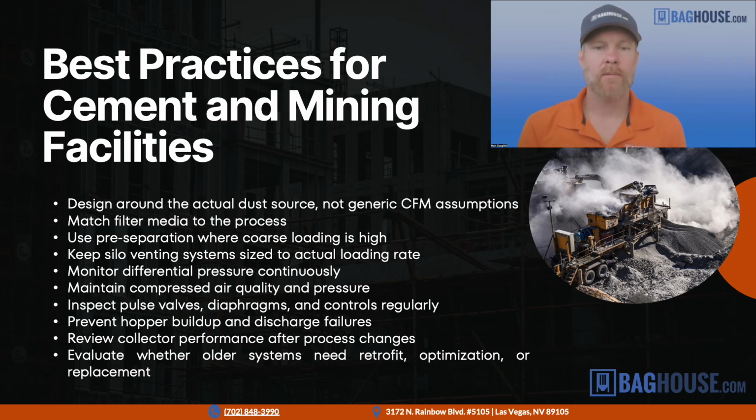Filter media is extremely important. Depending on where in the process you are, what type of material you're collecting and conveying, and the process parameters, heat and whatnot, the filter media can make or break the performance of your dust collection system. So temperature, moisture, abrasiveness, particle size, all of these things we talked about can influence the correct filter media for your dust collector. We may even want to have a cyclone pre-separator in front of it.